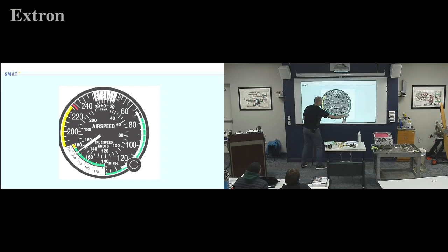So the pilot's going to turn this, and we said it's negative 15 Celsius. So he looked at the temperature gauge in the cockpit that said negative 15 Celsius and said, okay, I'm going to line up negative 15 Celsius with 10,000 feet. Now I have the correct numbers in here. So I know my mile per hour is correct. So my mile per hour is 203.